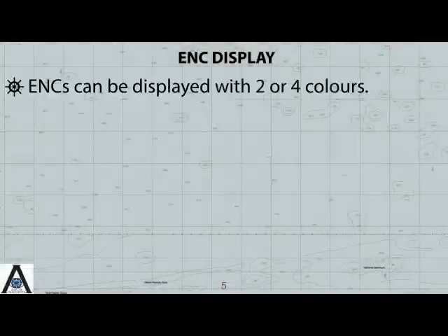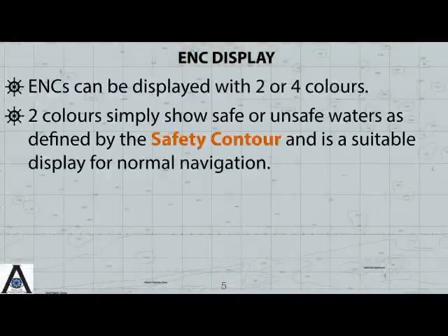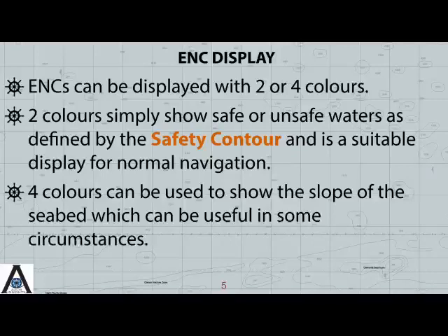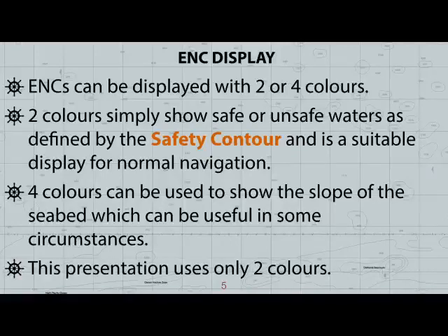ENCs can be displayed with 2 or 4 colors. 2 colors simply show safe or unsafe waters as defined by the safety contour, and is a suitable display for normal navigation. 4 colors can be used to show the slope of the seabed, which can be useful in some circumstances. This presentation uses only 2 colors.